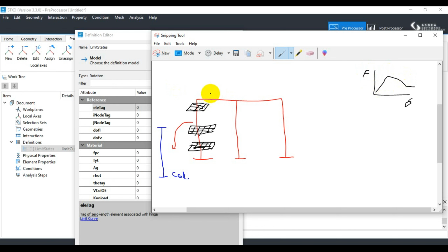If you are working with OpenSees, we have to define those fiber sections in the column in terms of those limit states, and assign special elements at these hinges, the joints, to consider them. If there exists some other failure mechanism that we are interested in, we can trigger it in those regions with a zero length element.